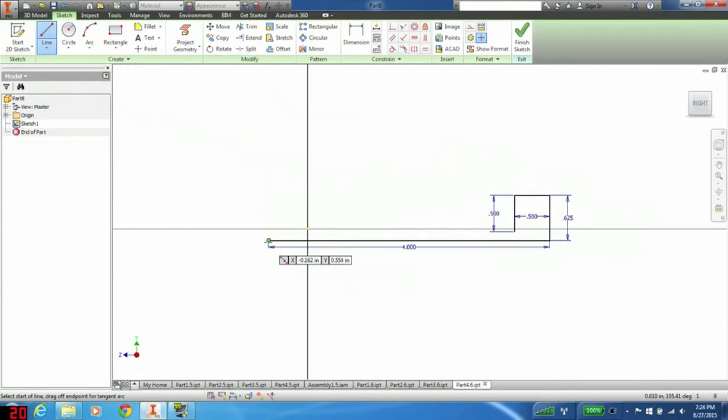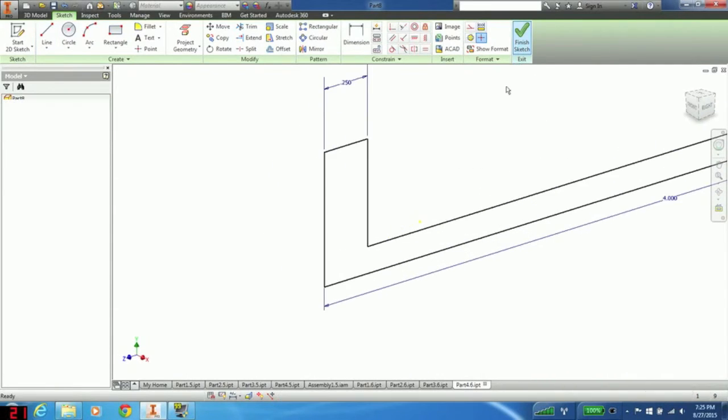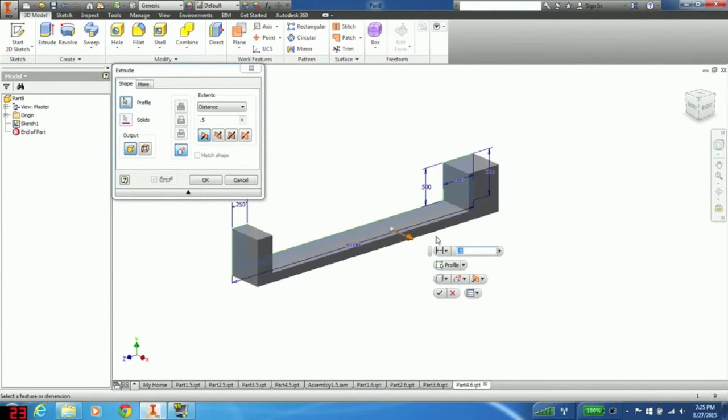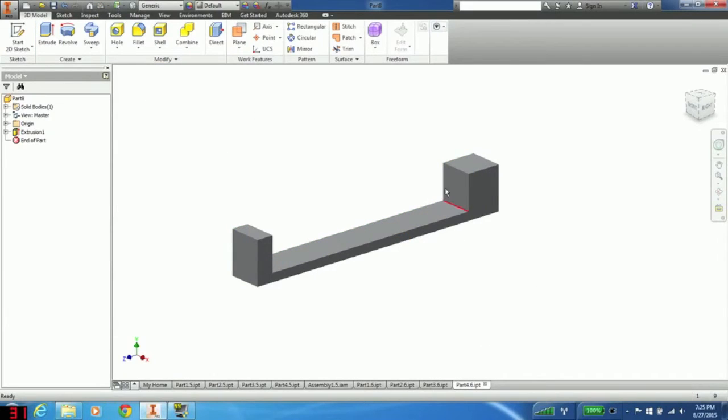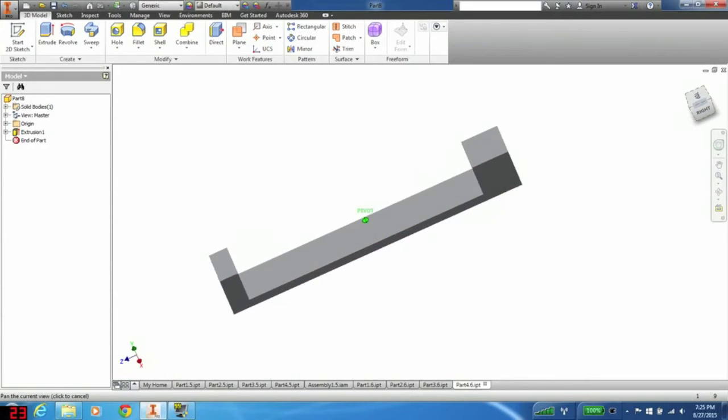Anyway, so I'm going to go over to the other edge, and I'm now going to go up to the same height, and I'm going to come in 1/4 of an inch, make sure that's horizontal, coming in 1/4 of an inch for the mounting for the handle. Then we're going to come down into that locks, and we're going to bring this across. Now we have our basic shape for the base, and we can extrude this entire thing to 1/2 an inch and click OK.